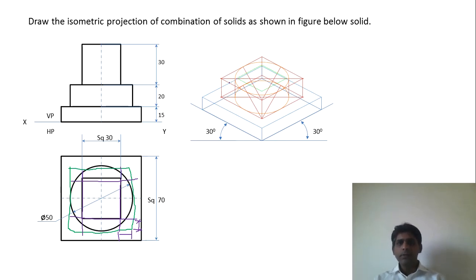So you can see that I can draw one arc here, whose length is equal to the isometric of this particular length. This length has to be measured from here, and then you have to mark the isometric lengths here, and the same should be done on this side also and on this side also. These are the arcs that I'm drawing, and you have to join the lines like this, and then this is the square that we are interested in.